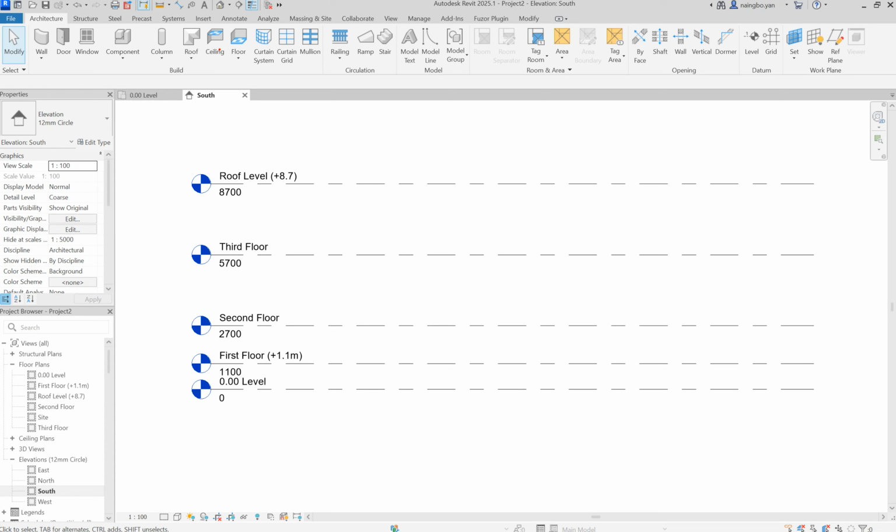So I will start the grid line. Go to the Architectural tab. This is the first step. Then we go to Grid. Since we are on the plan, this level cannot be seen, cannot do anything. So I will click Grid. I will start using the line from bottom to top. I can start from the C level, grid line 1. I don't bother about the distance. I just put 1, 2, 3. So it's easy for me.